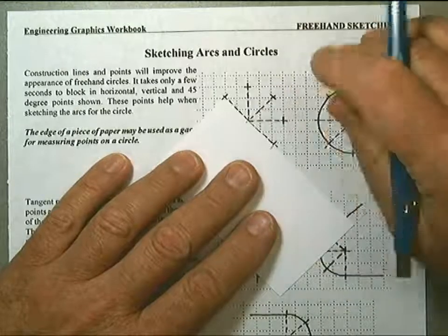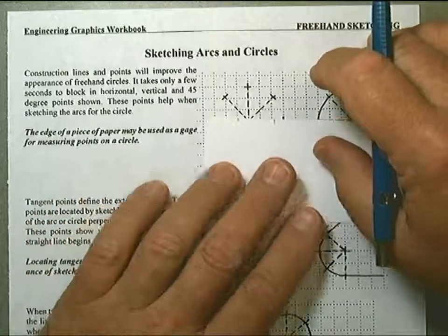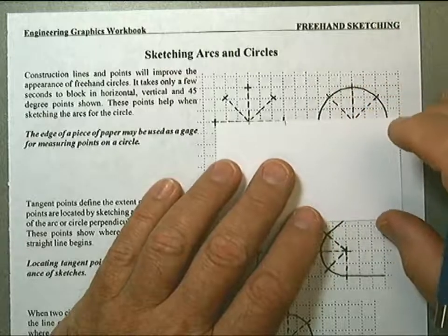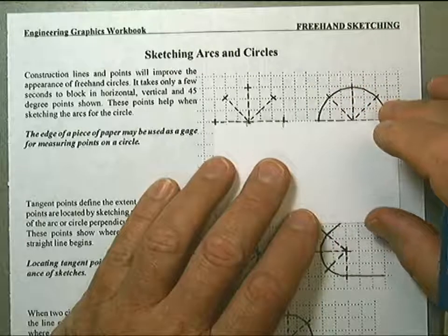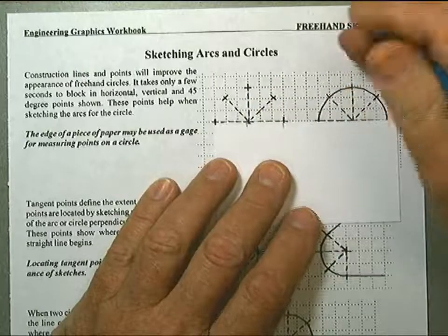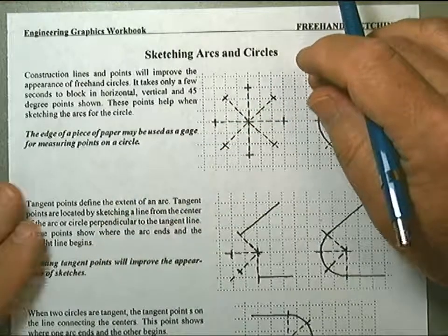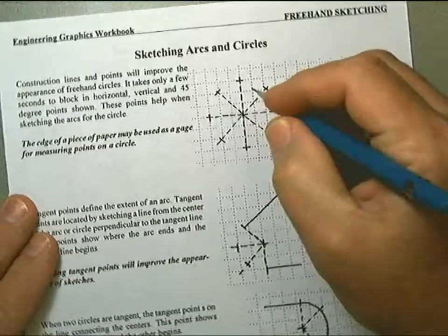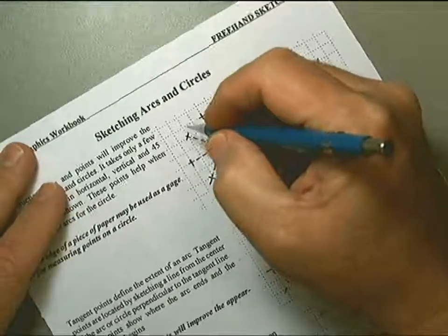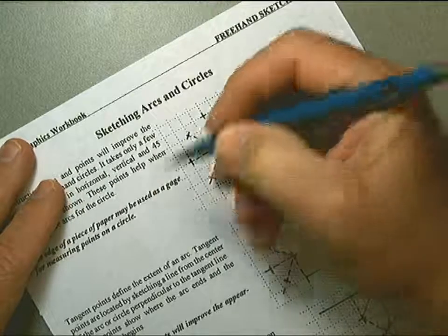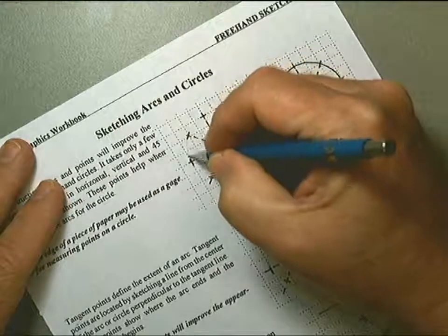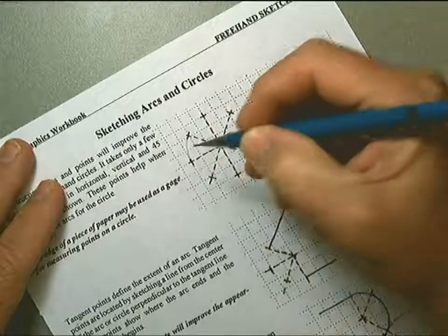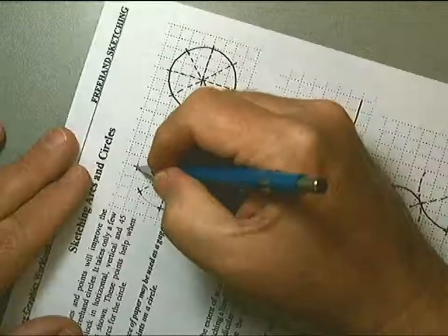and then using that, you will mark off 45-degree lines and, of course, the horizontal and vertical axis, and make little tick marks. And then it's a process of sketching a small arc, which most people can do. You'll need to turn the paper and position your pencil so that you can make a stroke, and you'll make a light one and work your way around.